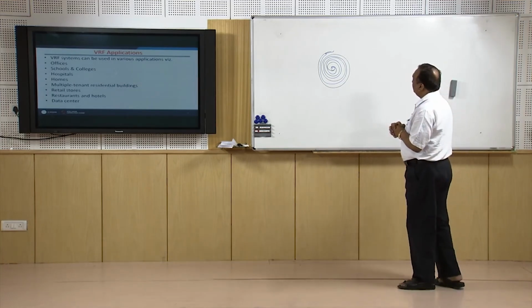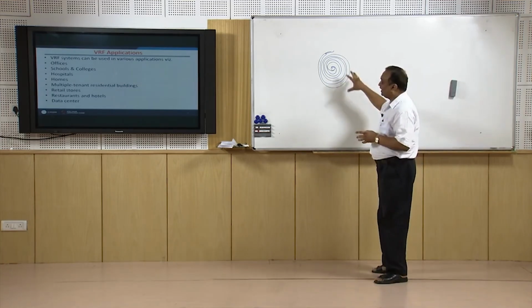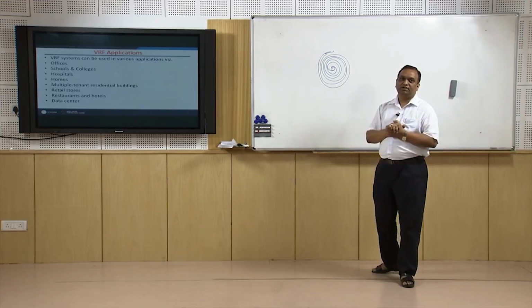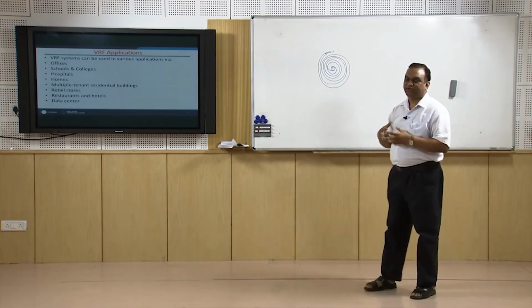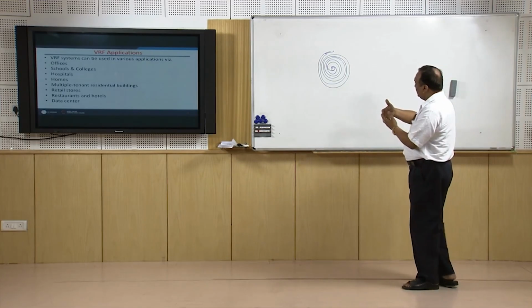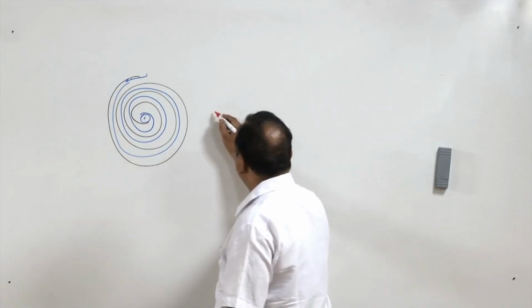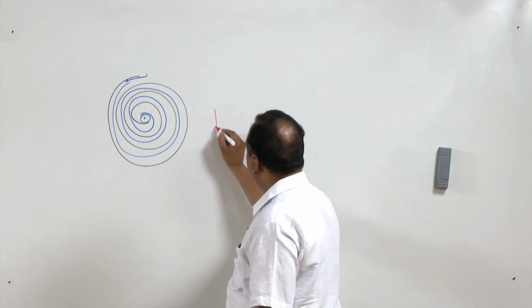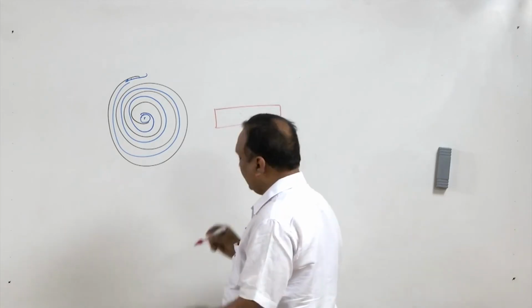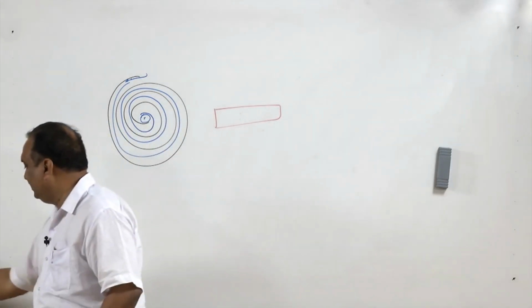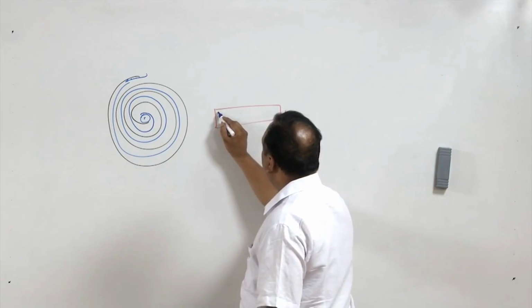Another type of technology in this VRF system is digital scroll technology. The spiral has a certain height, or depth, and the two spirals are engaged with each other to a certain depth.